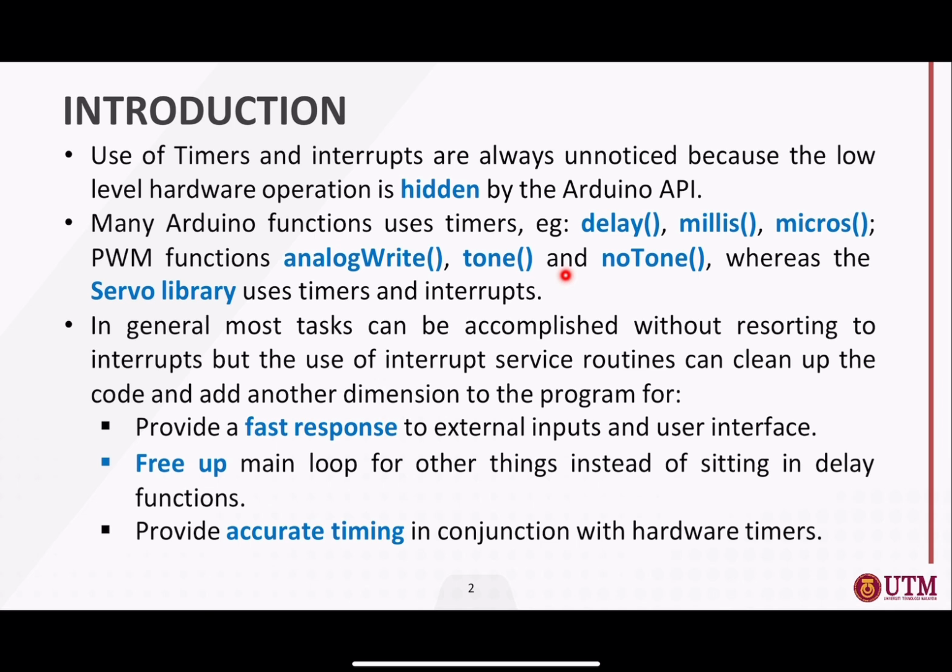Many Arduino functions such as delay, where you want to delay your LED blinking, millis and micros, where you want to get the current execution time of your Arduino, also the PWM function that you have learned in the previous class, analogWrite, and tone, which you use to sound the buzzers, as well as servo libraries, they also use timers and interrupts.